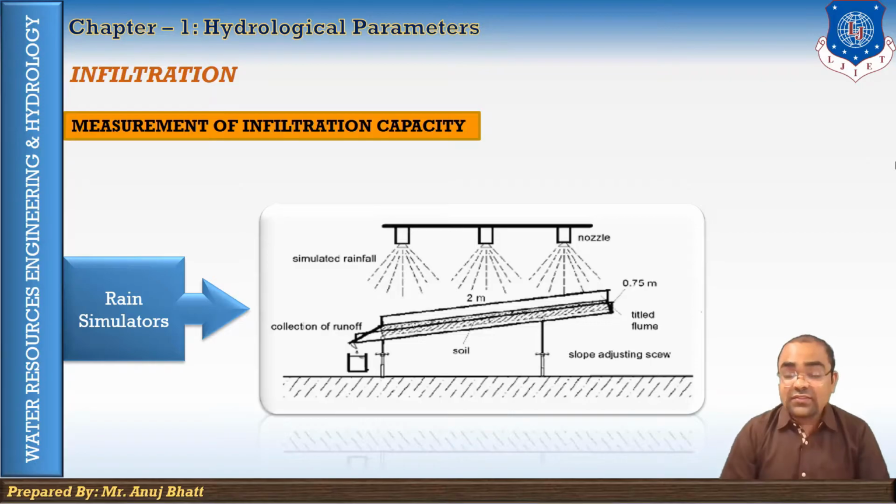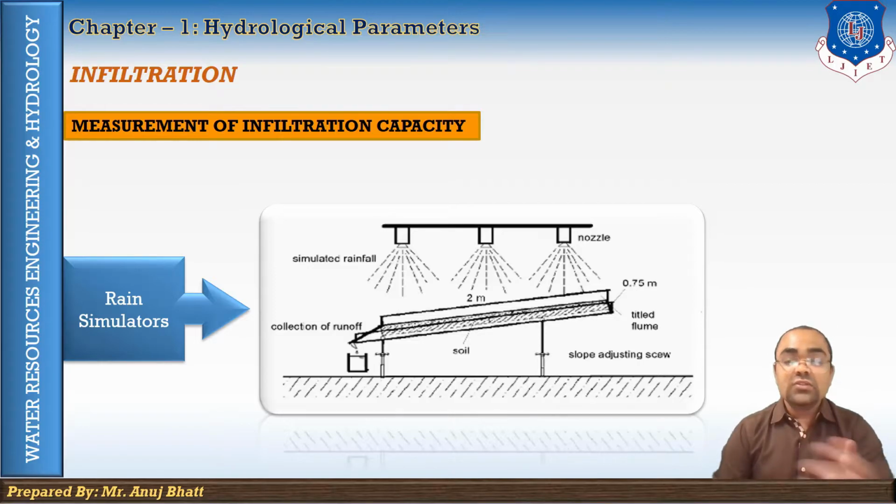In this formula all the terms are expressed as the depth of water over the plot, and the rate of infiltration can be determined from the total infiltration depth. Rainfall simulator type infiltrometers give a lower value than the flooding type infiltrometer. This is due to the effect of the rainfall impact and the turbidity of the surface water, which generally decrease the permeability. So this was the rain simulator, and previously we have discussed the flooding type of infiltrometer.